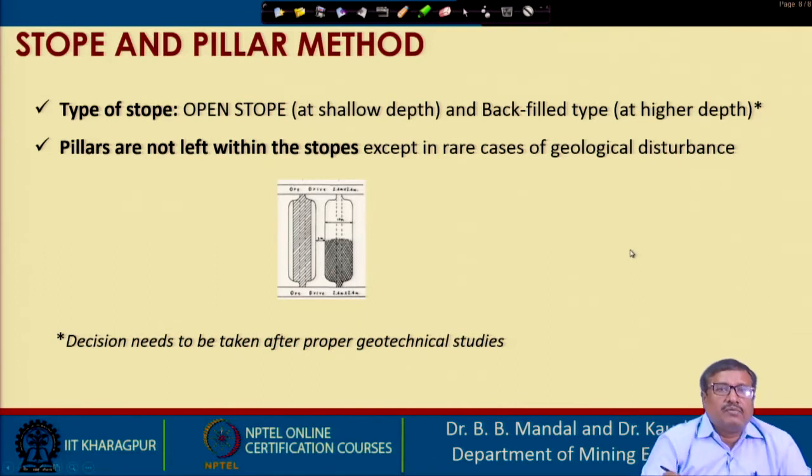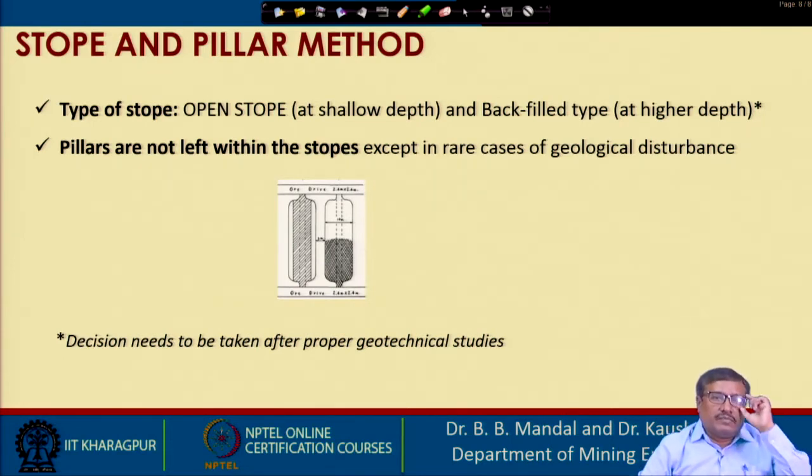But then how do you decide what kind of decision we should take, like should we go for open stope or should we go for the backfill type? That decision is taken once you have done the proper geotechnical studies, rock mechanics, the analytical part, and then only you decide whether we should go for backfilling, or we can keep it open, depending on many things.